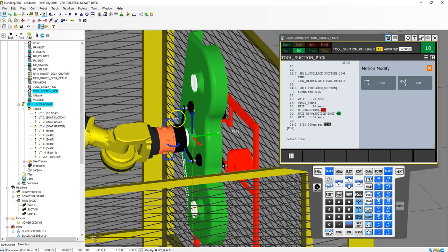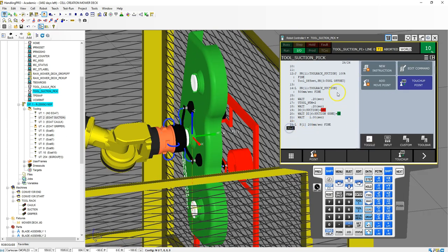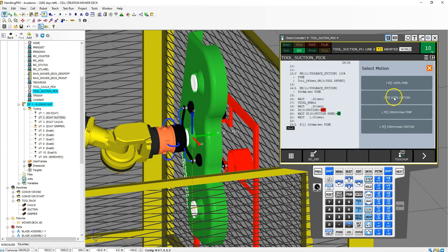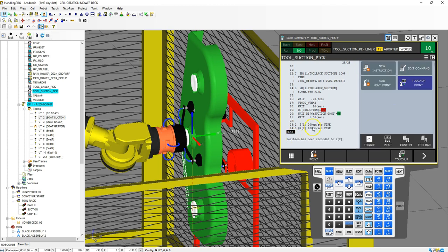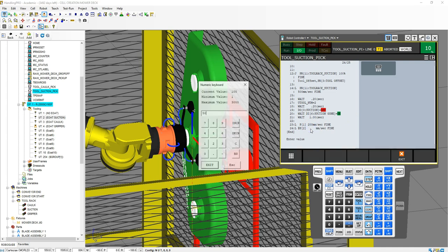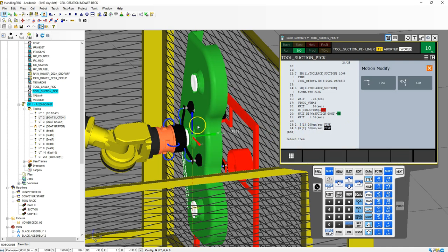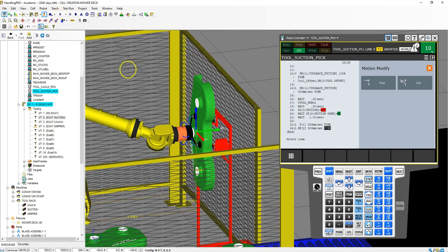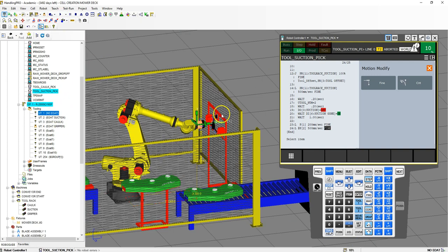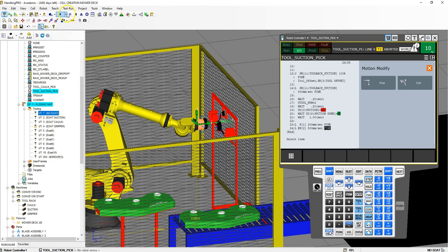So now we are away from that tool rack. So now we're going to go to end here, add move point. We're going to linear to this position at 500 millimeters per second. So we have position 2 now at that speed. So if we want to run this, let's go back to EOAT. Let's run the home program.